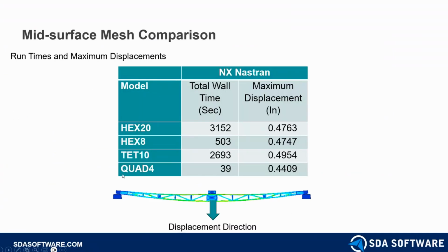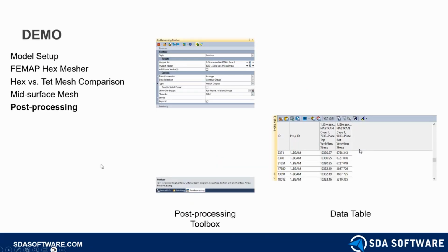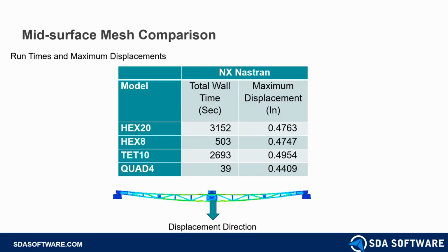All right. One of the questions that came in here is, does updating element thicknesses to solid automatically generate new properties? No, it does not. It will use the same property and update the element thicknesses. There are other tools for generating separate properties, so there are other options. We can definitely discuss offline on that.